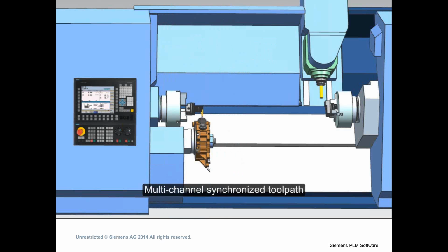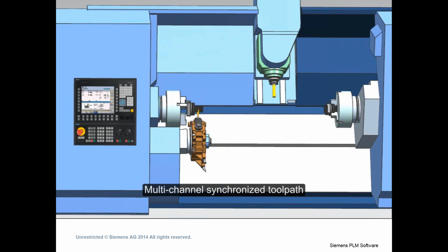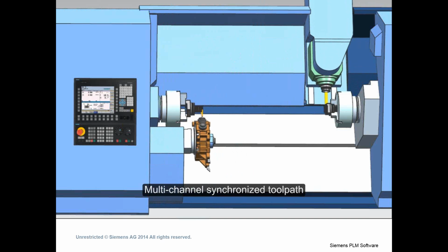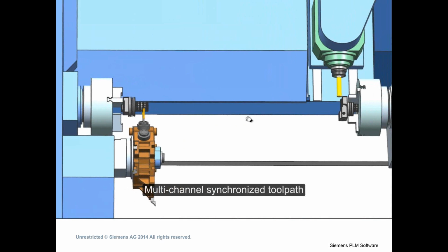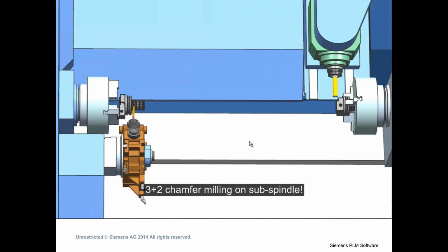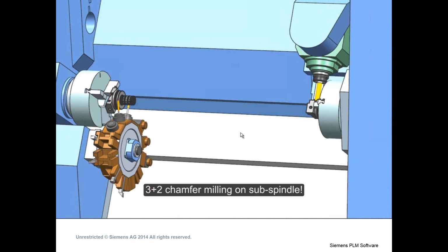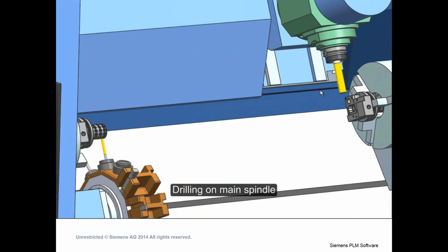We will continue on by drilling on the main spindle and milling operations on the sub-spindle, continually programming on the end of our part, creating the part contours, relief areas, and holes on the head of the part, while we're still drilling 60 holes on the main spindle, thus saving valuable program and machine time across multiple machines.